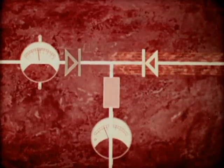The collector current is very large. The base current, although smaller than the collector current, is, due to the many surface recombinations, larger than with a transistor operating in the normal state. The reverse bias applied to the emitter-base junction is not consistent with a comparatively large emitter current flowing.